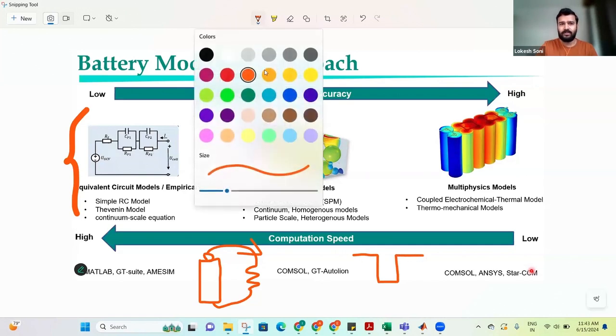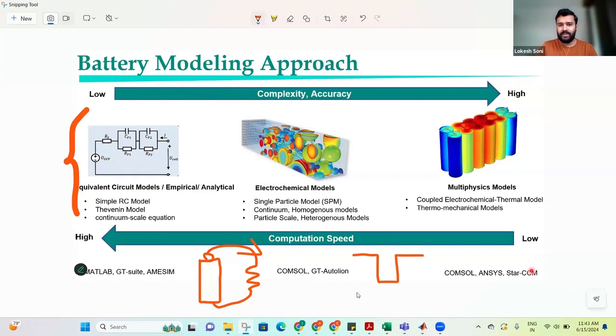What you will observe is the voltage of the cell, let's say it was at 4 volts, will show this sort of behavior at the terminals. So the intent is very simple. We want to mimic this behavior through some electrical circuit. What we realize is that combining a resistor and capacitor in some sort of combination will help us mimic this character.